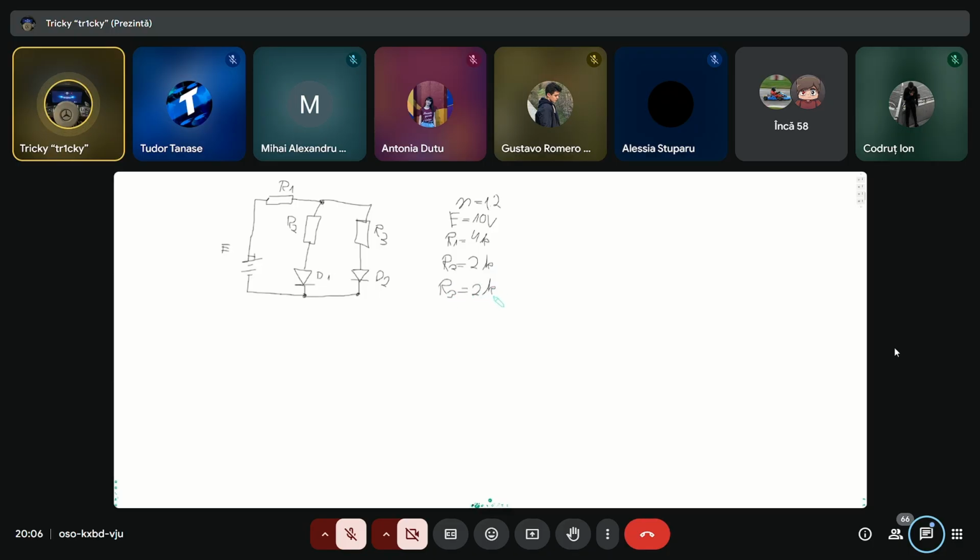As we can see here, both diodes have the anode on top and the cathode on bottom, so this is called forward bias, right? So you're gonna draw both arrows in this direction, and you're gonna start by declaring that VD1, and you can write a small 2 here as well, are both bigger than 0, which means that they are on.